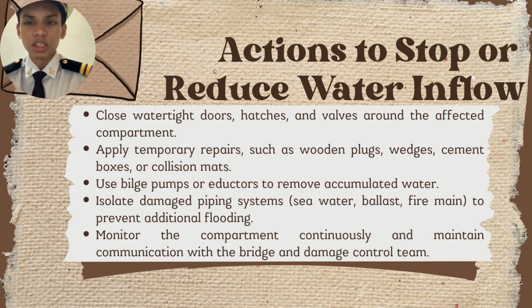You also have to isolate the damaged piping systems of the seawater, ballast, or fire main piping systems to prevent additional flooding. Last but not least, monitor the compartment continuously and maintain communication with the bridge and damage control team.